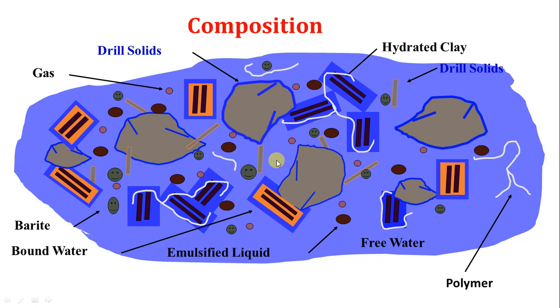So the percent of solids determines the efficiency of the mud and also the efficiency of the whole drilling operation. So the solid analysis is a very important point.